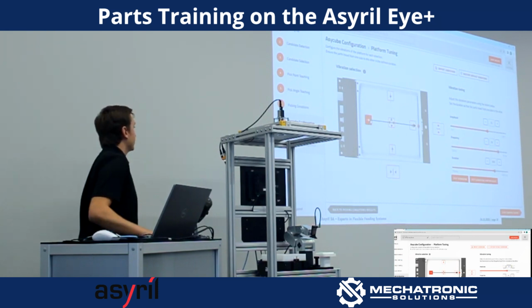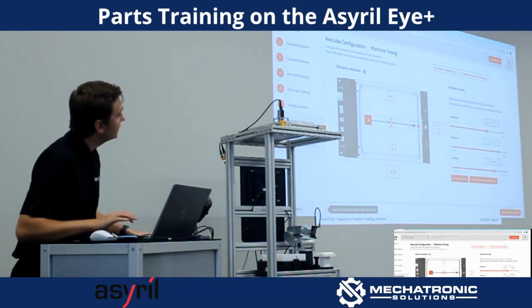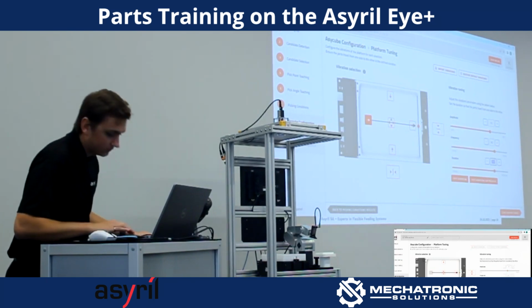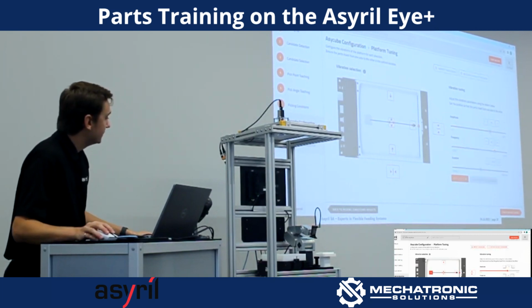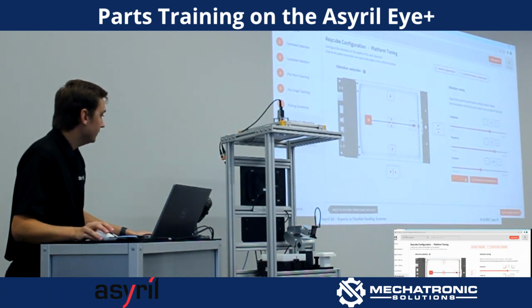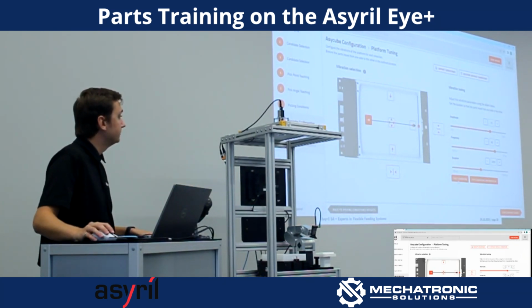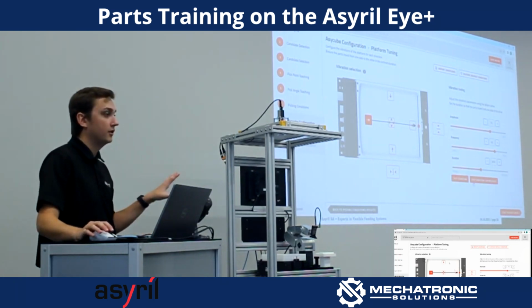So I'll just do a quick test here. Maybe increase this to 70. It's down to 64. See how 2000 is, and we can test the vibration here. When I hit test vibration, it'll move parts across the ASYcube. That seemed to work pretty well. You can also test the vibration continuously. When you do this, it'll turn on until you stop it.